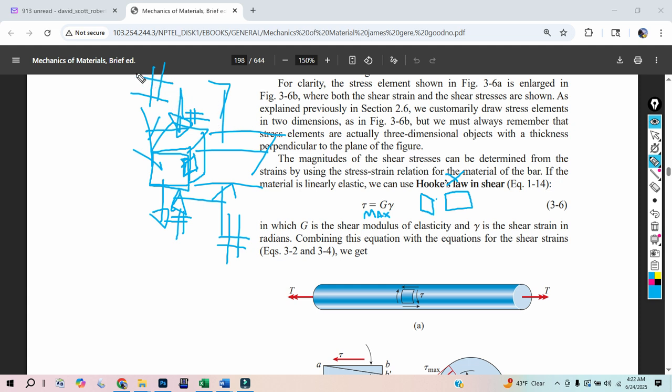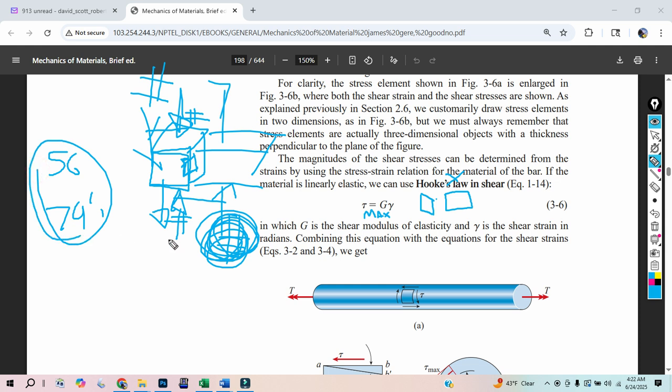And because we're doubling up on the force, that is one aspect where shear, this quantity, this number in shear, is less, can be 56% to 79% of the tension value, you know, 20% different. But yeah, that's the range that shear is going to happen easier than being pulled apart in tension. Cool.